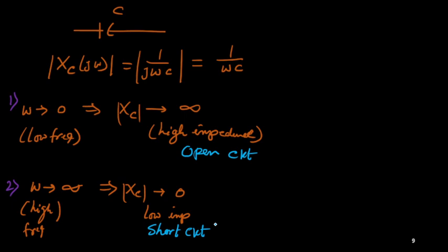So in short, what I am saying is that for very low frequency, the capacitor will behave as open circuit. For very high frequency, the capacitor will behave as short circuit. Okay, this is a very useful concept. For inductor, it is just the opposite.